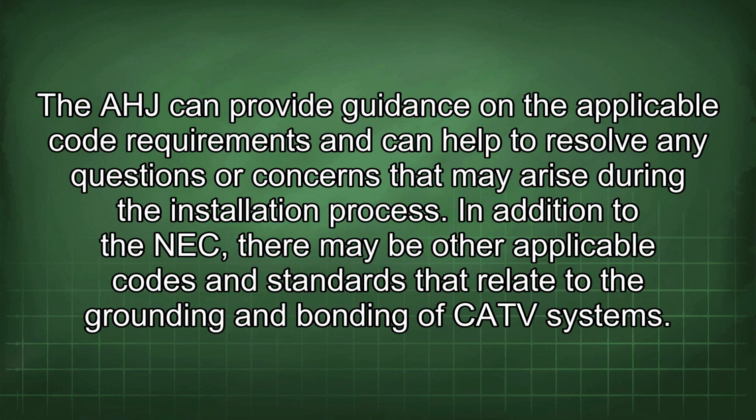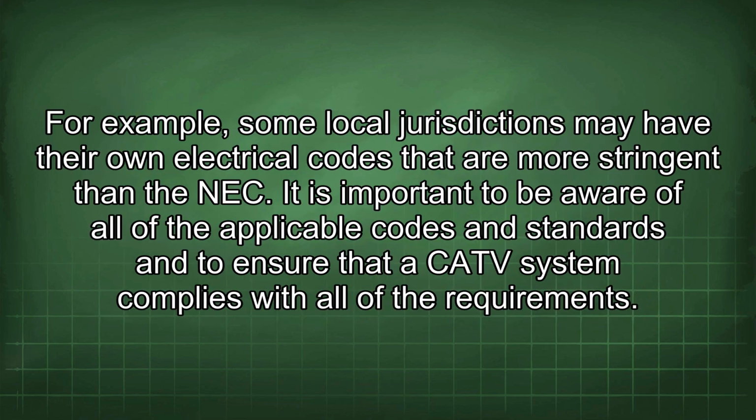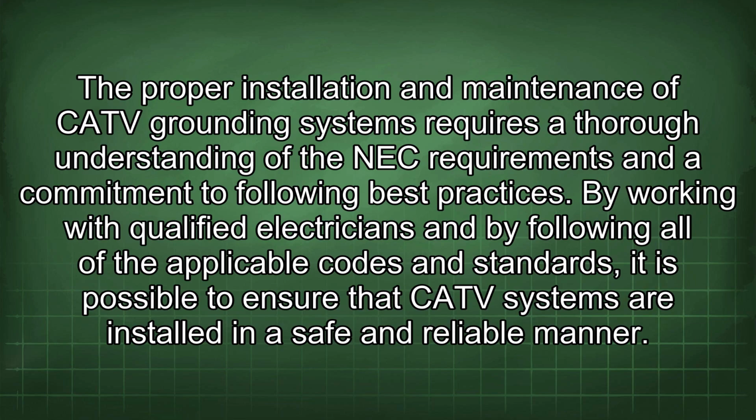In addition to the NEC, there may be other applicable codes and standards that relate to the grounding and bonding of CATV systems. For example, some local jurisdictions may have their own electrical codes that are more stringent than the NEC. It is important to be aware of all of the applicable codes and standards and to ensure that a CATV system complies with all of the requirements. The proper installation and maintenance of CATV grounding systems requires a thorough understanding of the NEC requirements and a commitment to following best practices. By working with qualified electricians and by following all of the applicable codes and standards, it is possible to ensure that CATV systems are installed in a safe and reliable manner.